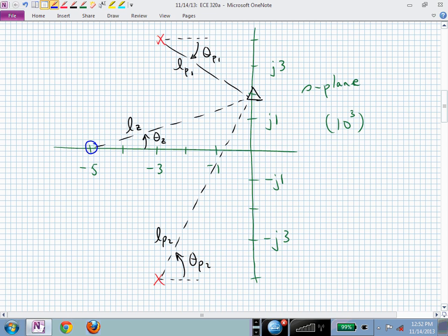It's not our zeros, is it? It's our poles. Our poles are what we have in the denominator when we do our partial fraction expansion. So if you get lost, just say, wait a minute, I can think of this as a partial fraction expansion. And then I have all of these pole factors giving me contributions to my system response. And the ones that I'm interested in are those that are associated with my transfer function H of s.